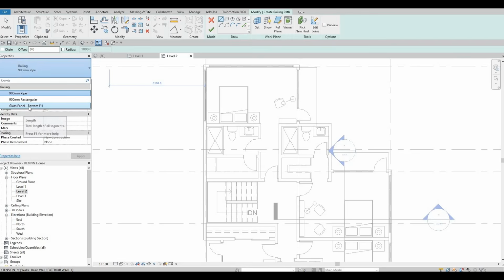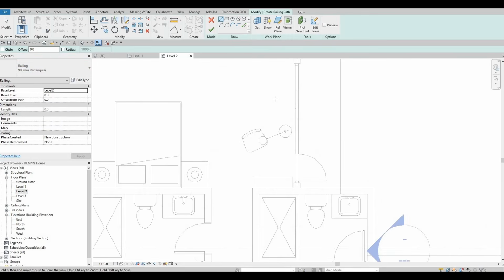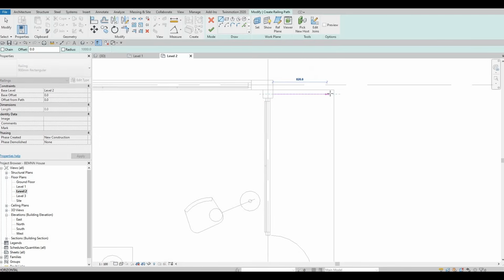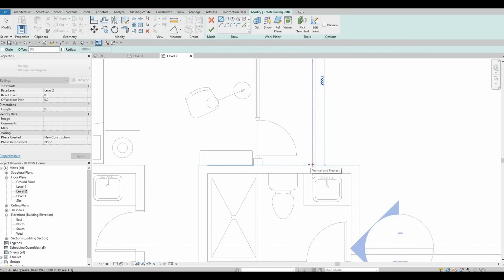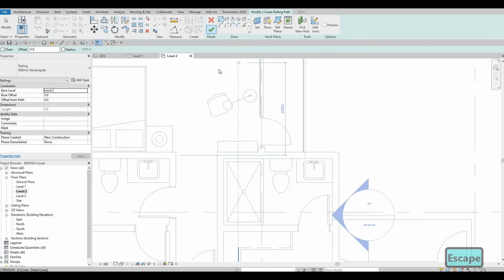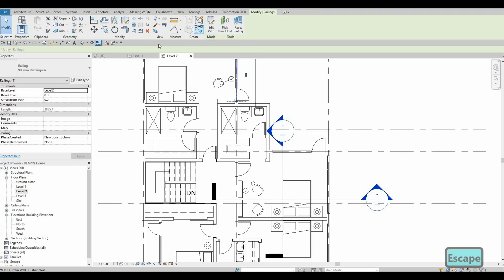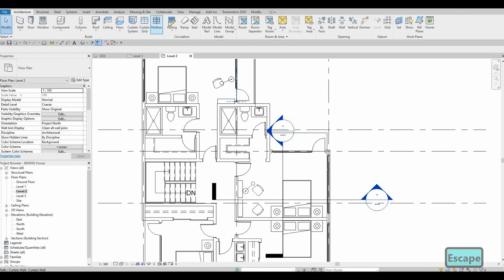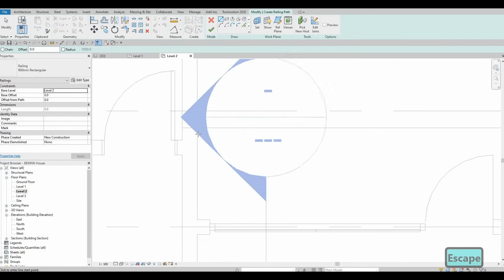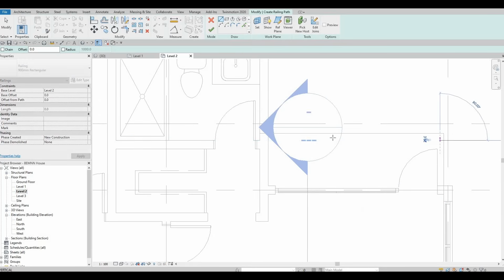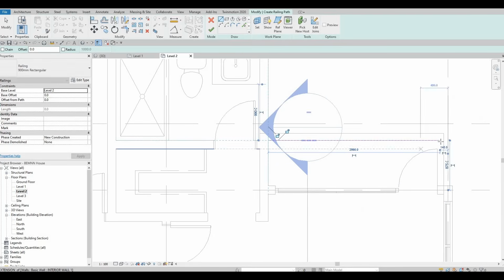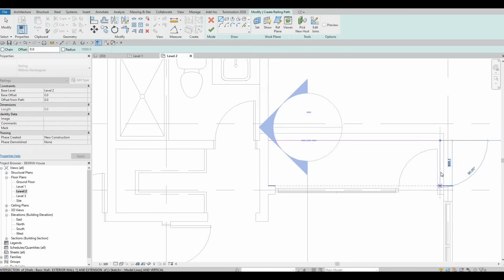So you need to go to architecture, click on railing, and we have 3 different kinds. What I want right now is just rectangular, and then here you just need to add those like this, but you need to add them one at a time. So click finish. Here we need to do that again, so click on the railing, add it right there, and then going right here.